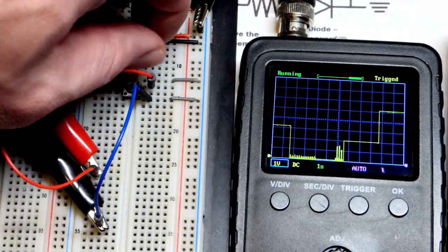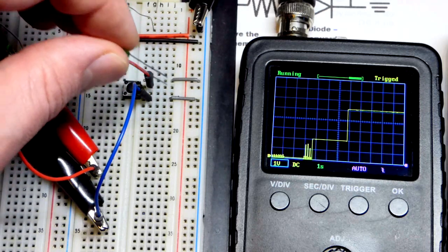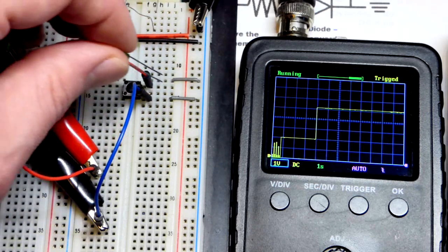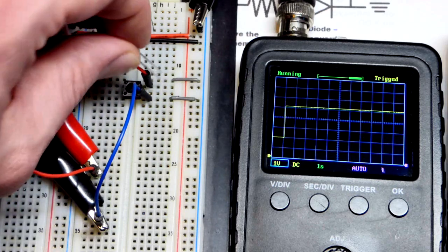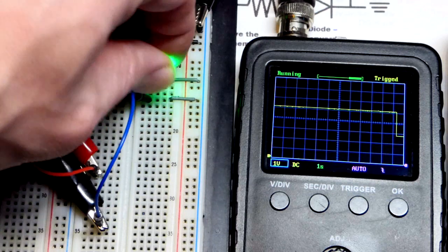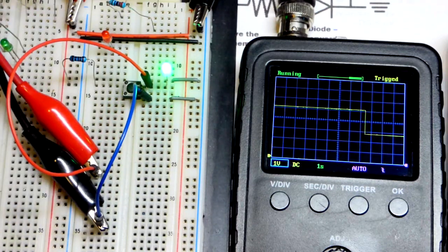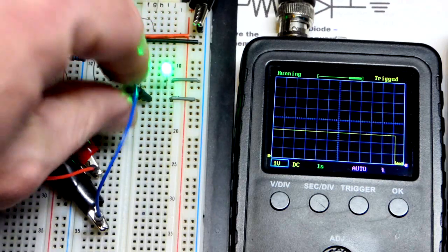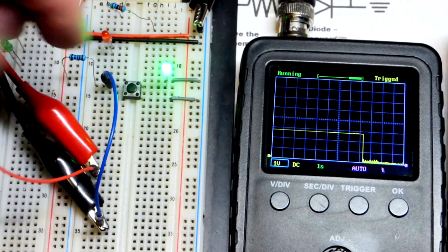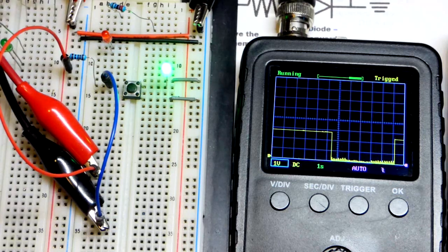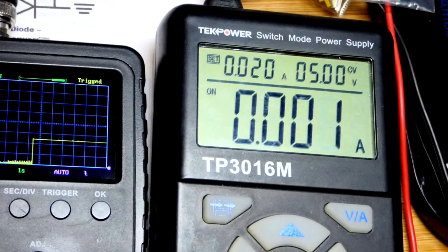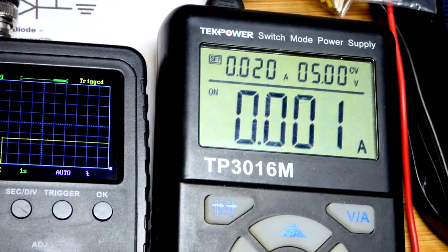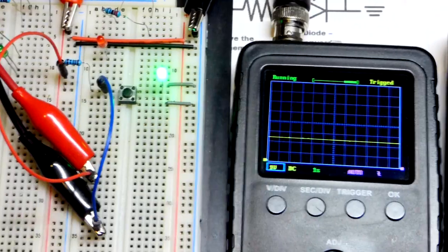I'm going to grab the green LED, and again, this is a bit unusual for my videos, but negative is higher up than positive for the LED. So long lead, the anode, is down 1 row, short lead, the cathode, up 1 row. It's a green LED. It's a lot brighter, but it has more voltage across it. That's not why it's brighter. It's just naturally brighter. What is setting the current is the resistor again. So we'll look at that voltage. This is a video about voltages. And there you can see we have a little more than 2 volts right there. And the power supply, although it's not accurate, shows clearly lower current than before. So that's the main takeaway.